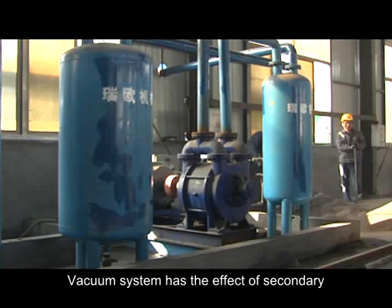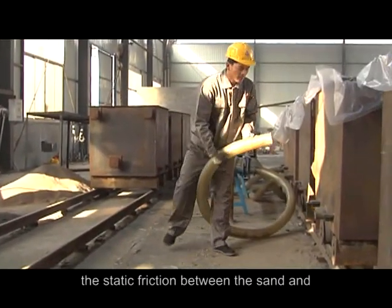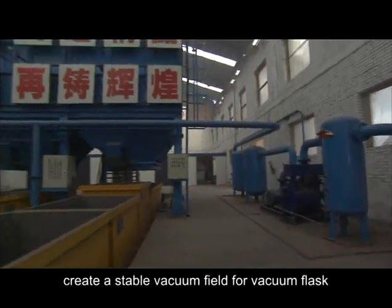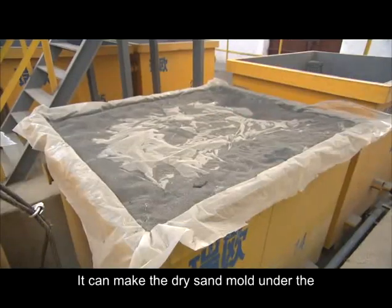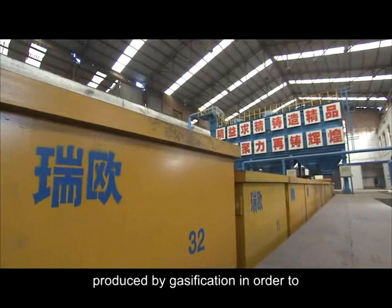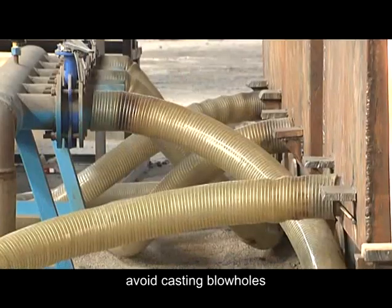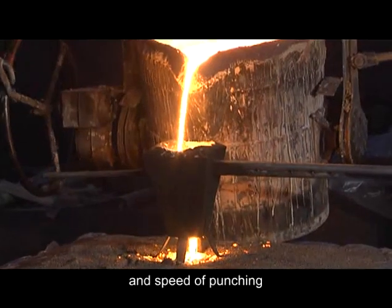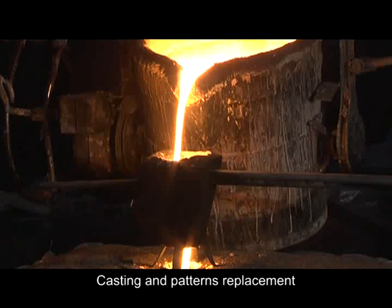The vacuum system has the effect of secondary compaction of foundry sand. It can enhance the static friction between the sand and create a stable vacuum field for the vacuum flask. It can keep the dry sand fixed under the atmospheric pressure and suck the EPS model gas produced by gasification in order to avoid casting blowholes. It can increase the flow rate of molten iron and the speed of punching, thereby increasing casting yield.